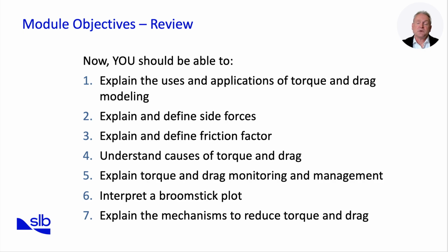In this submodule, we have focused on understanding how side forces, stiffness, and buckling behavior affect drill string mechanics. We began by calculating sidewall forces by combining pipe tension, section length, and curvature. This allowed us to quantify the lateral loading acting on the borehole wall. We then worked through an example showing how to calculate side force for a given section and how limiting dogleg severity reduces the risk of excessive contact loads.